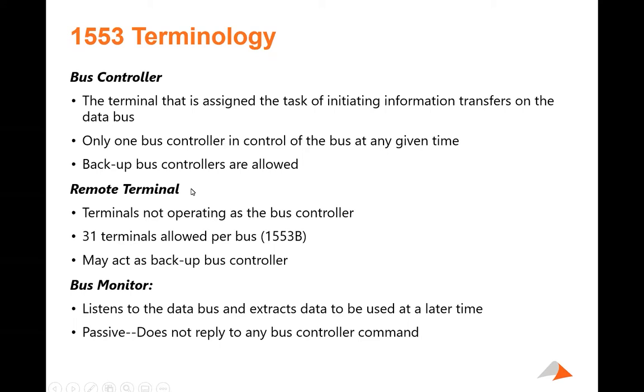Again, the remote terminals. You can set up a remote terminal as a backup bus controller, but remote terminals are never bus controllers as a whole. I have seen people take that and make it a bus controller. I wouldn't advise it. What I really recommend is that you have a monitor that is your backup bus controller, because monitors listen to everything, and then you'd be able to keep up on all the data and operations that are occurring, where a terminal may not be quite so bright. Up to 31 terminals are allowed on 1553 currently.